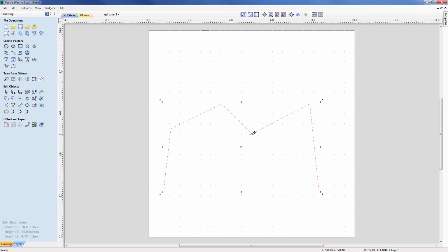As you well know, this is a 10 by 10 part, and you can see that we've moved that to exactly the midpoint on the screen. So that's just the different ways that we can move an item. By moving it incrementally in X and Y along the direction that we want to move. We can also do it incrementally by adding an X and a Y, like 3, 2, or we can do this by specifying an absolute position. In this case, we use, for instance, 5X, 5Y without the comma, and that moved the whole item together, where I was moving the original control point from whatever position it was in to 5, 5.